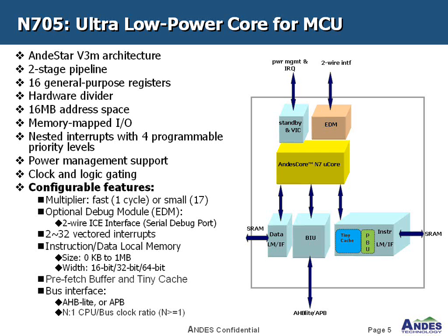The other important configuration is instruction and data local memory. It is an SRAM interface. This interface needs only 1 cycle to fetch instructions and access data in SRAM. So the interface can improve the performance of your system. Besides, the user can connect flash or ROM to this interface and boot up the system from this interface.